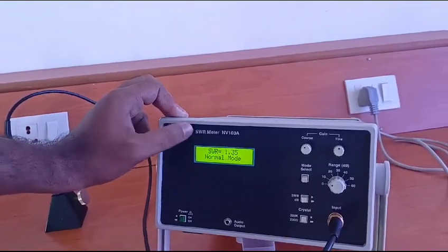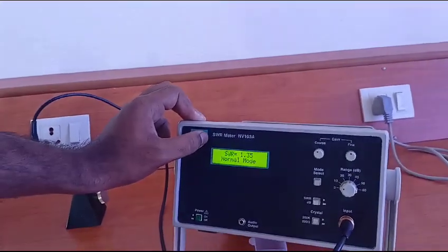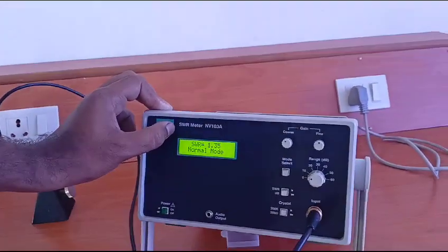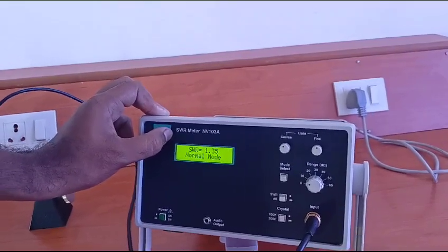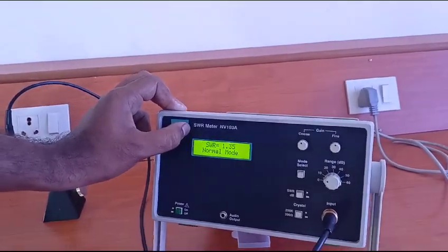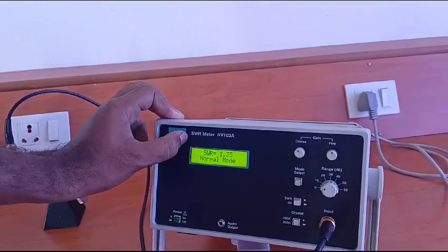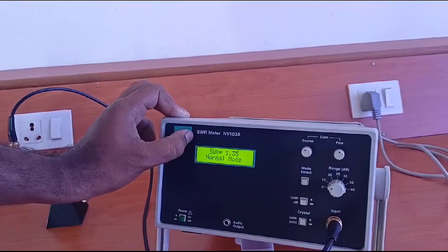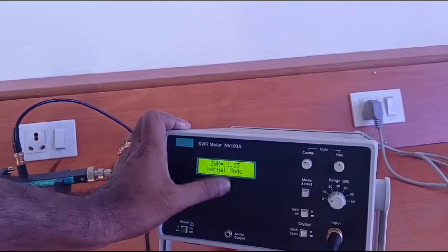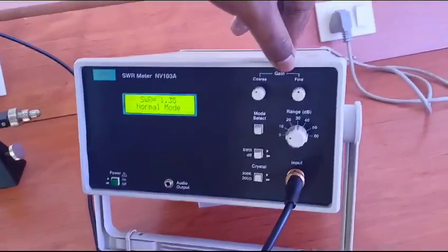SWR is the standing wave ratio. In a microwave signal or transmission line, standing wave ratio is very important. You should keep the SWR value as close to 1 as possible. If the SWR value rises from 1 to high, it means that the transmission line or power section does not match perfectly. We always care about the SWR meter, and it always shows a value close to 1, that is, the minimum value. Then we should also keep the gain at a mid value.